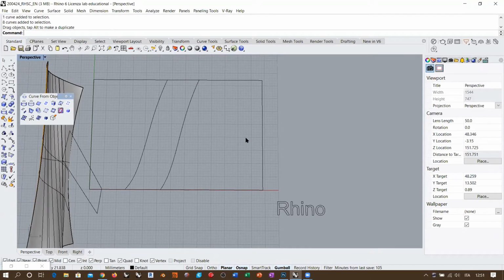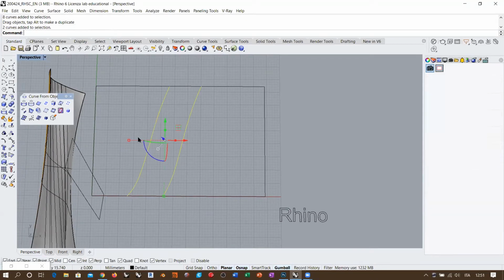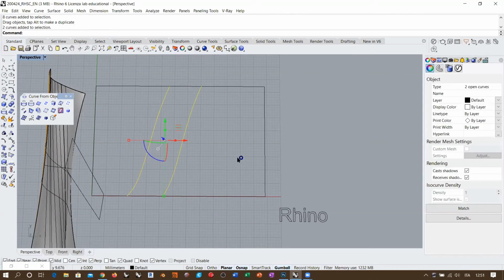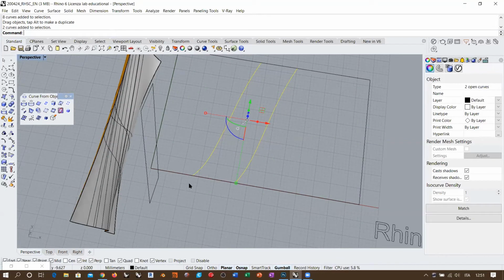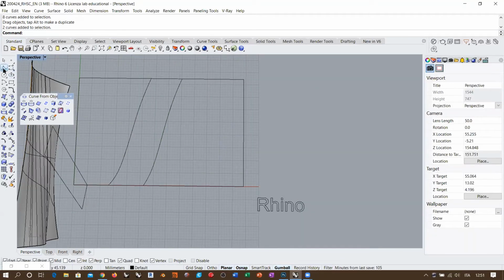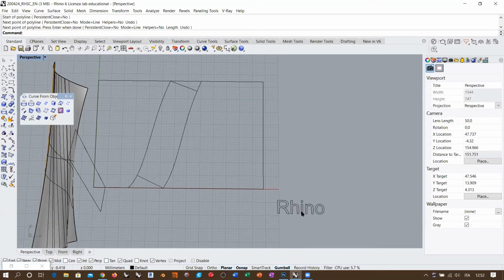So, for example, I need to place the text inside this stripe right now in order to later bring it onto the double curvature surface. So the first problem is how I draw a text inside this area. The way I can do this is like this. Draw a line which is perpendicular to this, and another line which is perpendicular to this. So the area which will contain this text is going to be this one.